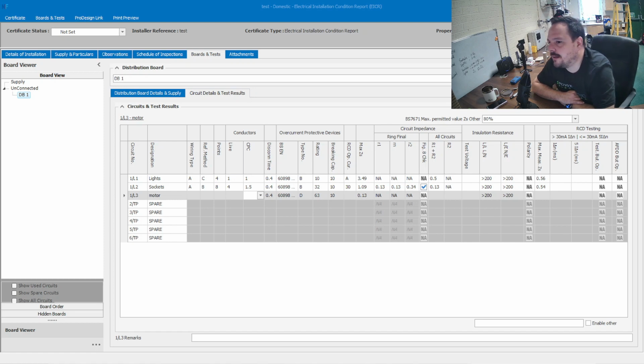But if you were on an EICR, for example, you know, if you're lucky, you'll have the information from the original design which will show you what the impedance was at that point, so the recorded value of ZE. And you've seen in my unit here, I've recorded different values on different days. It's not a set figure, it does move around due to what's going on in the distributor's network. And then you come along and do your ZE measurement and do your calculation, and that figure can actually be above what's allowed.